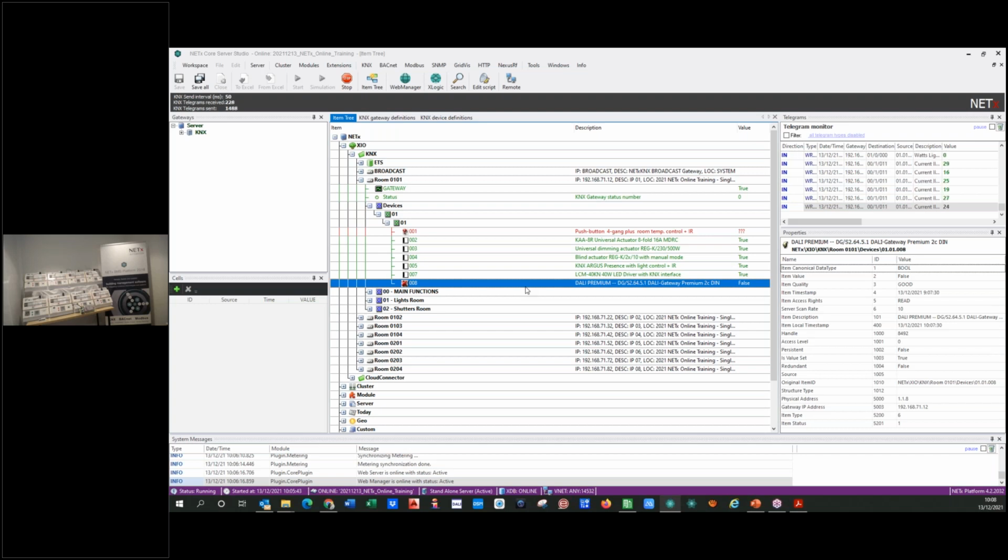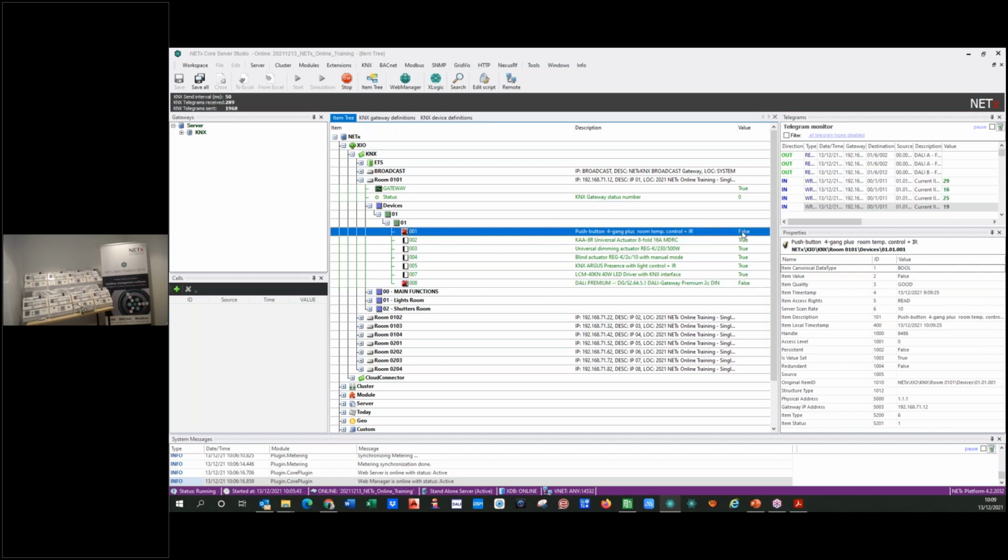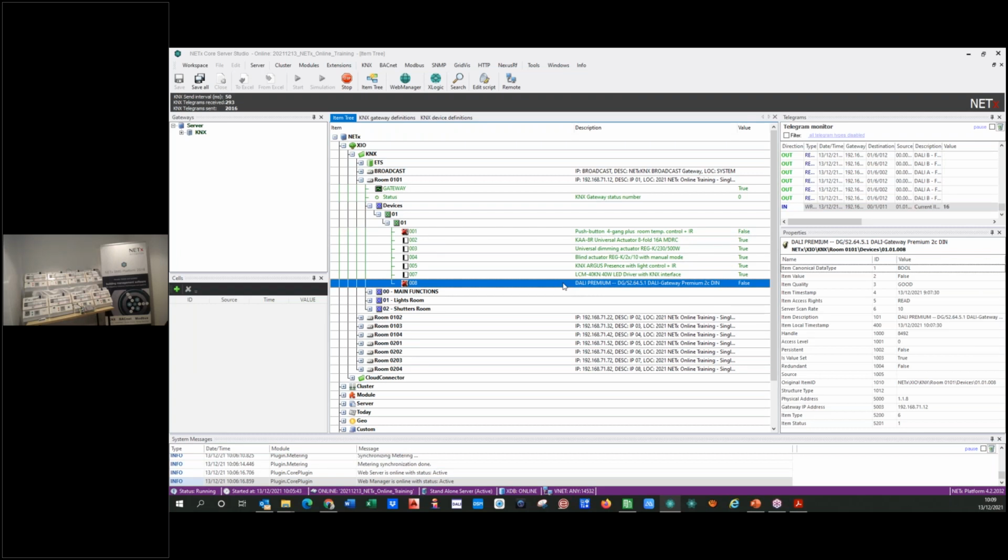And then, this is important, we can configure, for example, an alarm, a message to the end customer, or maybe an alarm to the maintenance service that some push button is not present in the installation, and we will need to go to that room and check what is happening. And then you call your guest and you say, I'm sorry, but we have discovered some issue in your room. If you don't mind, we have to check. And if the end customer has taken the push button, he will put it back to the location for sure. It's not a towel, but it's possible to realize. So you see that it's in false value now, and this is a possible trigger of an alarm, for example. I will put it back again.